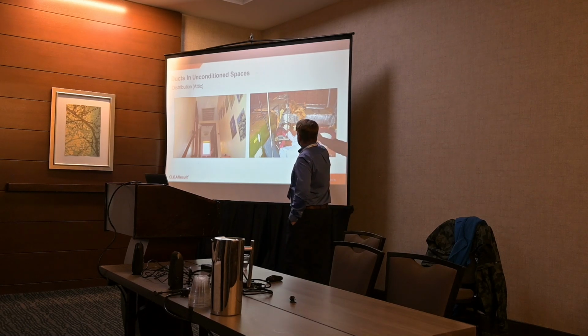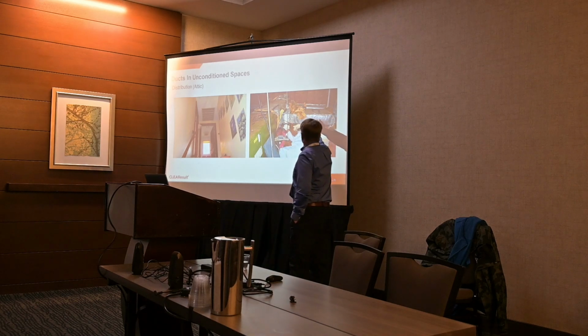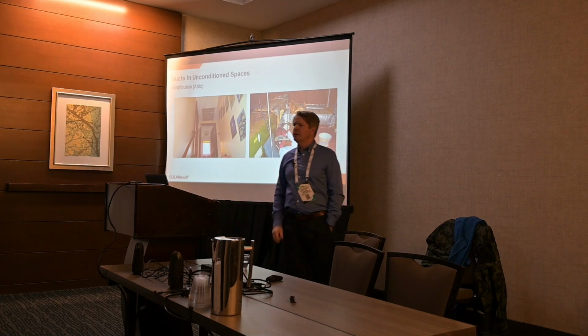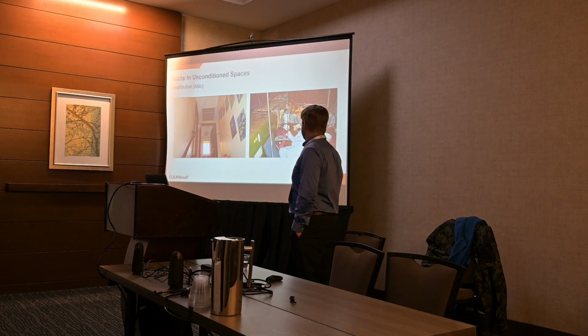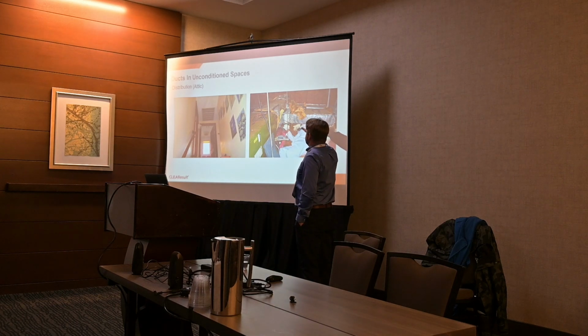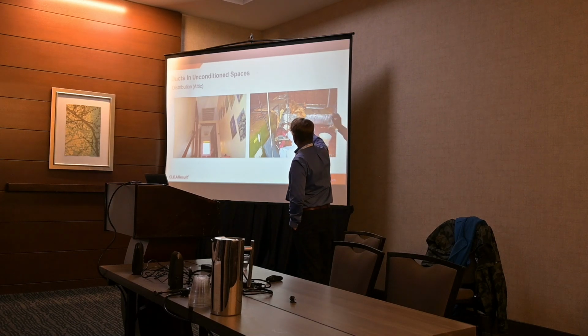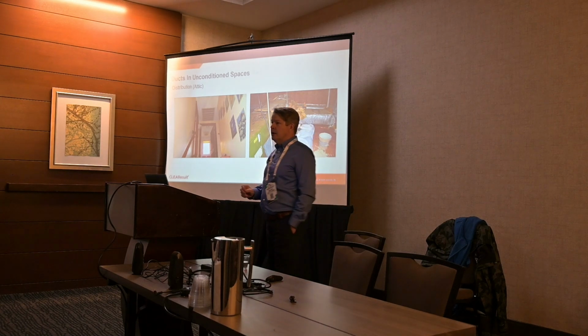Okay, so we can see this poor soul is underneath that insulation there. Should we save that insulation? What should we do with that insulation? Yeah, take it off, get rid of it. Because what it's really doing is just stopping us from accessing a bunch of leaks, right? And it's in terrible shape. You can see it's really old, it's fallen apart. He's ripped it up. Just take it off, seal that duct system as absolutely tight as you possibly can, and then insulate it at least to code.